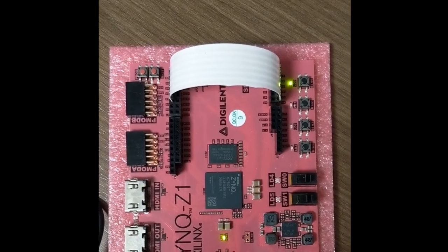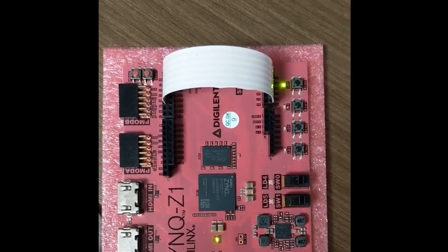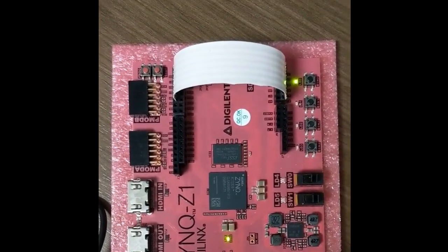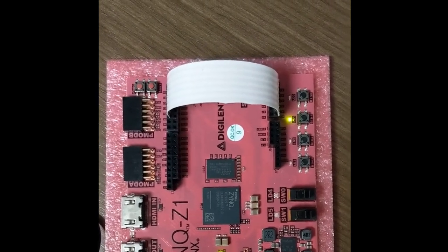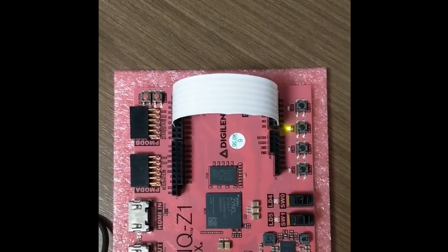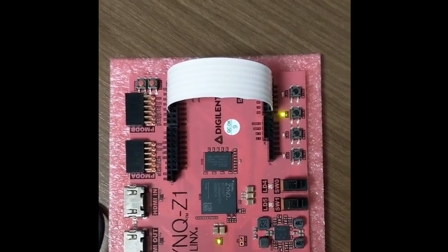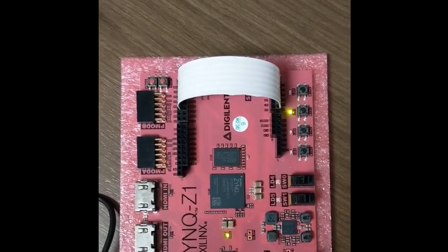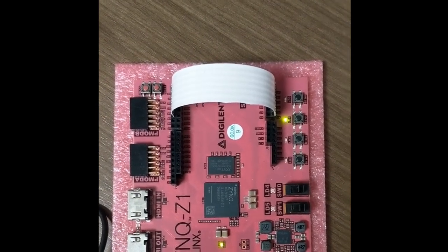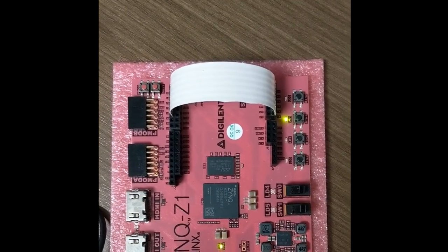So what you're seeing is that each LED has a duty cycle of 50%, but they're offset because we can't display all of the output on one LED because that would require 6 different inputs for the logic function. So what you saw there is that the first LED was on for 8 seconds and the second LED was on for 8 seconds, and they're interleaved. So that's just to show you that the function is working correctly and we've correctly implemented the multiplexer.